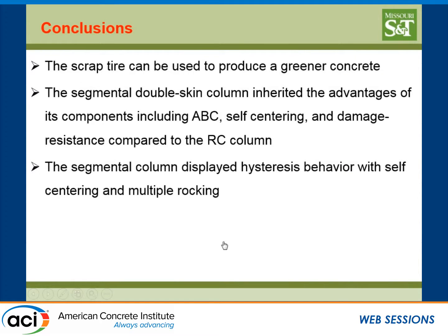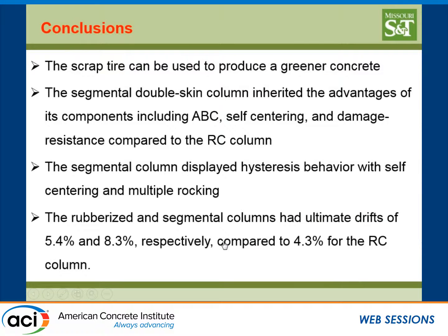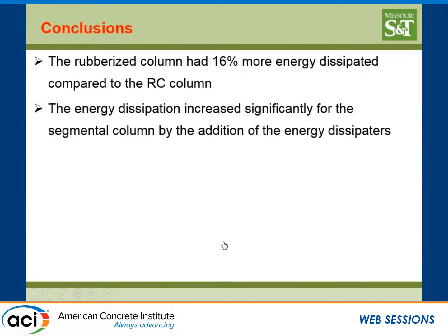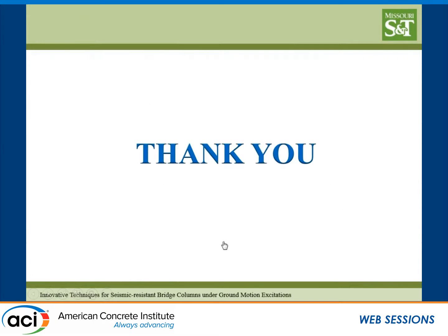The segmental column has a more flag-shaped hysteretic behavior. That means we have self-centering with small energy dissipation, and this is why we substitute with some external dissipators. The rubberized concrete increased energy dissipation by 16%, and I just would like to thank you so much.